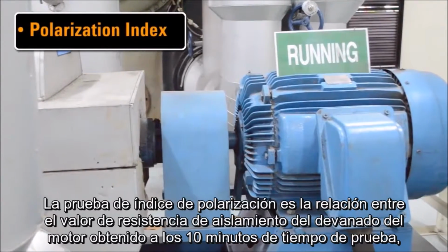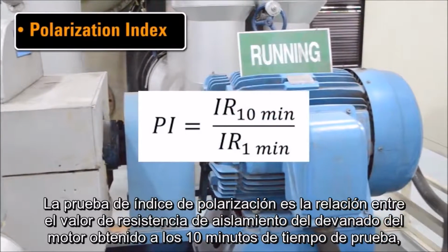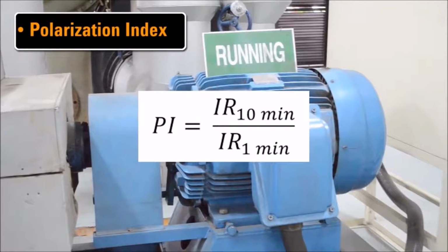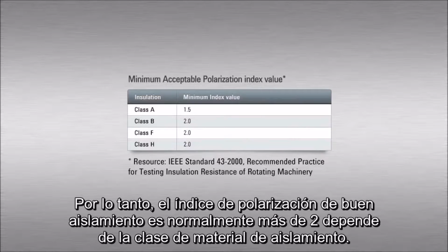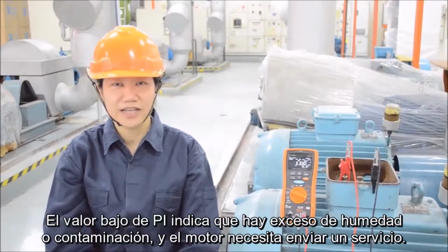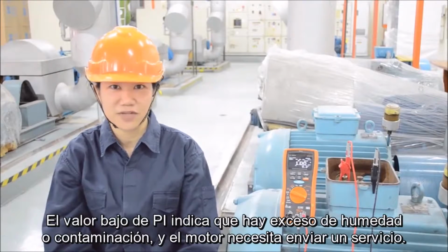The polarization index test is the ratio of the motor winding insulation resistance value obtained at 10 minutes test time over the value obtained at 1 minute test time. Good insulation shows a continuous increase of resistance over a period of time. Therefore, the polarization index of good insulation is normally more than 2, depending on the insulation material class. A low PI value indicates there is excess moisture or contamination and the motor needs to be sent for service.